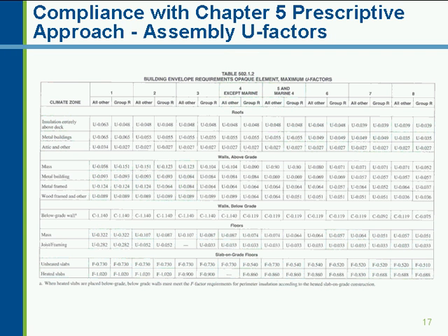And you can actually mix and match this. Parts of the assemblies in the building can meet the R value requirements for insulation only. Other parts of the building can actually meet the U-factor requirements for an assembly that can't meet the R value for insulation. So this gives you another approach that wasn't in the 2006 code requirements.